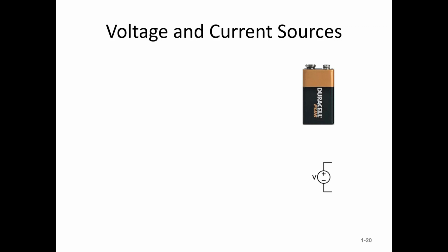Like many of you may have built a computer. You have a power supply in that computer, right? I've got a big old, time to brag, 750 watt power supply, because I love power, and you know, power is my graphic card, so I can sling pixels all over the screen and record videos and play video games. But it behaves like an ideal source. That is, it puts out a couple different voltages, 12 volts, 5 volts, maybe some others. And those voltages are pretty much constant. So it's close to an ideal source. But many other simpler sources are not ideal.